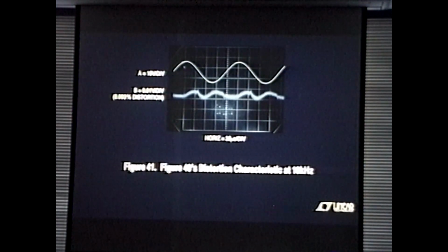This is the distortion of the multi-ranging circuit at 10 kilohertz, and again you end up with about 30 parts per million. You can see a little bit of crossover, and what appears to be the waveform of 2F. And I can tell you right now, whenever you build a sine wave oscillator and you look at the distortion that rolls out, leading the parade is 2F. That's always the case. Regardless of the mechanism, 2F is the leading offender.